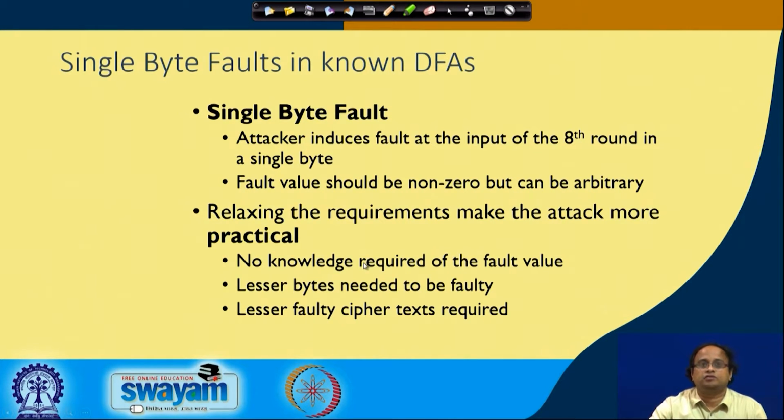Because remember, when you are actually doing an attack in the real world, you do not exactly have control over the fault. So, you try several fault injections, and maybe luckily one of them falls into your desired fault model. So, it is important that you develop a DFA which requires a lesser number of faults, because then the probability of getting such a fault is enhanced.